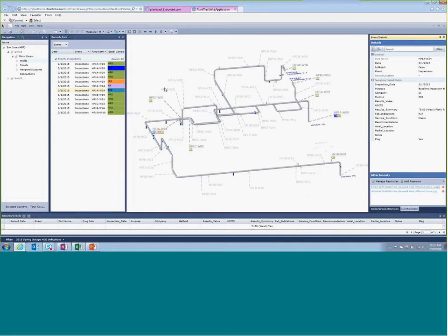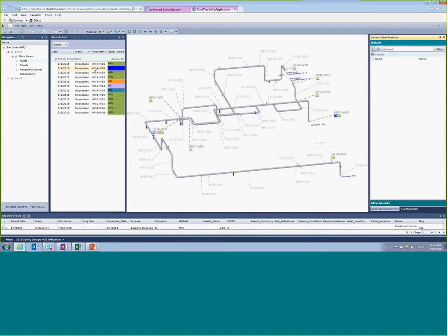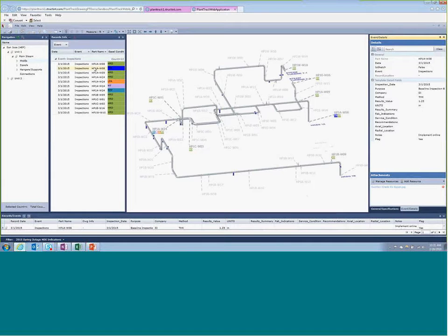So one of the things, to this particular weld, if I transition over to weld 8, we could see we had hardness, which came up as 150 now, which is pretty problematic for grade 91. And one of the things that was unique is that when we started inspecting, we noted this other spool here, let me highlight this, was found to have globally low wall thickness. So either something happened from the manufacturer, but having a low hardness and a low wall thickness can really cause a problem from a creep standpoint, because now the pressure-driven hoop stress on the spool is going to have a more profound effect.